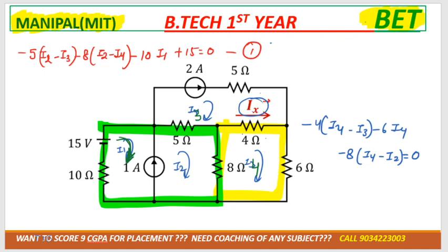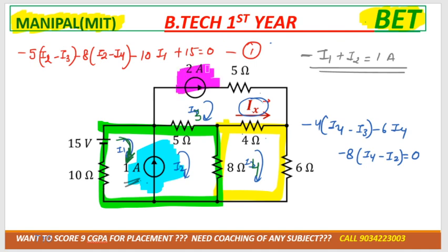Now the next equation we need to make from the current source. As you know, this current source is in the middle branch, so i1 and the 1 ampere are opposite. That would be minus i1 plus i2 is equal to 1 ampere. Its value is 1. Now we'll make the equation from the other current source. The other current source is 2 ampere, and as you can see, that 2 ampere is in the corner branch, and in the corner branch there is a flow of a single current.